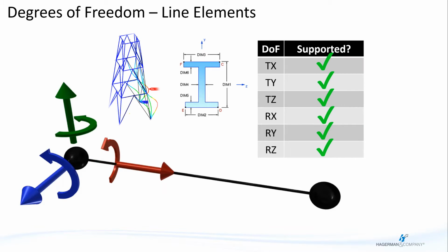Our basic building blocks for highly idealized structures: the bar, beam, and pipe elements. These guys are great for representing long, uniform cross-section structural members. Why mesh a beam with thousands of solid elements when there are textbook formulas governing their deflections? Use just a few line elements, also known as 1D or one-dimensional elements, and you'll get good results at a fraction of the cost.